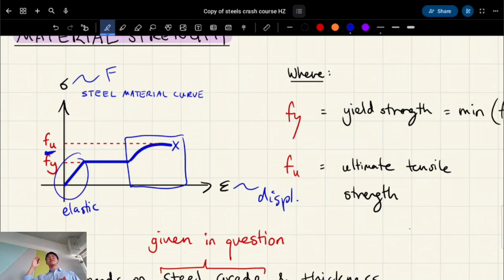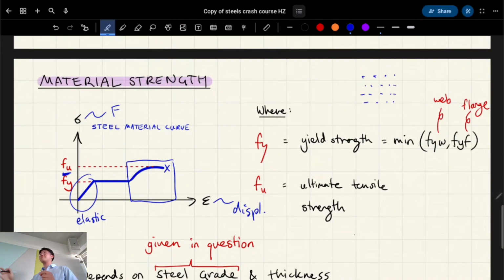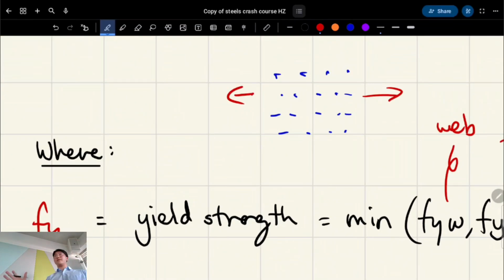So essentially, with metals, do you guys remember chemistry and stuff? If you haven't done material science, you have a metallic lattice, right? These little ions that are connected to each other, a sea of electrons, all that, right? So the idea is, let's just talk about tension. As you pull these apart, they're going to dislocate, right? But then the dislocations start impeding the other dislocations. And so they're actually resisting their own dislocating, if that makes sense.